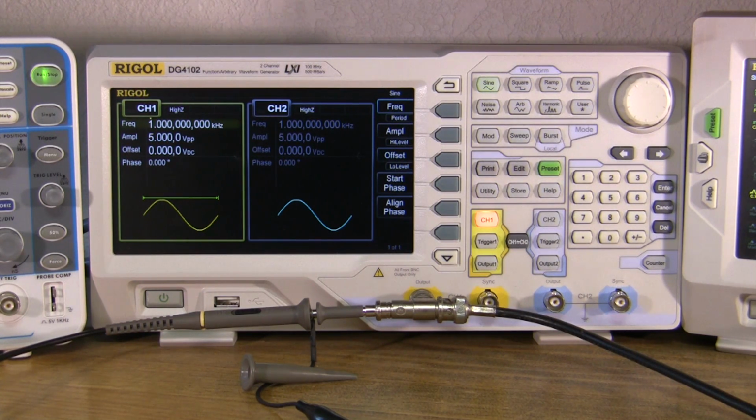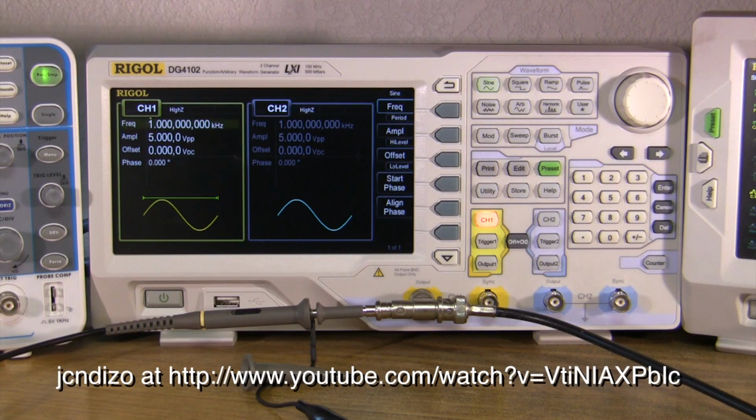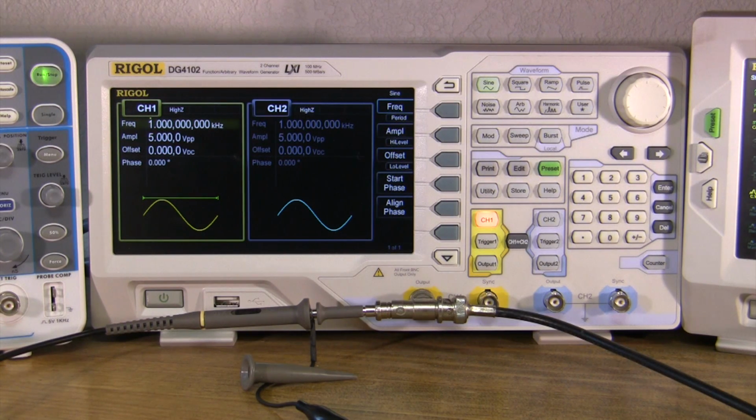On the screen you'll see a website where someone goes stepping through all of the functions this thing has as far as arbitrary waveforms. Since he's done a pretty good job of that, I figure you can go there and look at some of that. But I'm going to go back to the modulated signal levels from this generator, because that's more in my interest area of radio frequency, IF frequencies, and so forth. As you see, we have 1 kilohertz frequency at an amplitude of 5 volts peak to peak here.